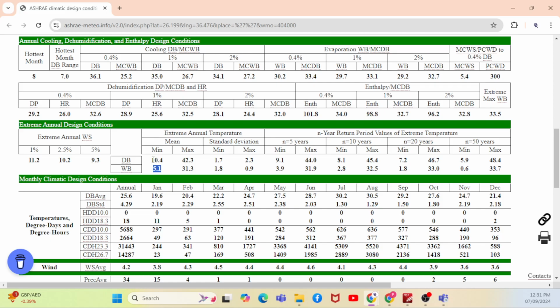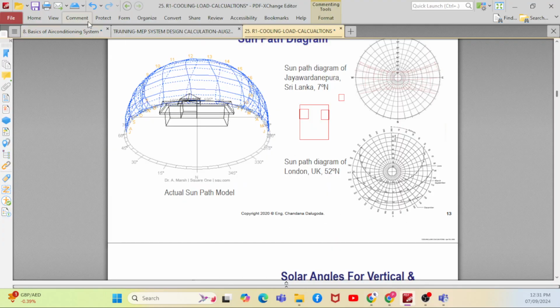When you talk about winter outside, this is the outside temperature, 10.4 degrees Celsius. Similarly, it is the same case. Just now, whatever we have calculated, what is the heat inside? The heat coming from occupants will not change during winter and during summer, right? Whatever heat you have from your body, it will emit the same heat. Maybe it will vary depending upon the activity, but the amount of heat will be much more equivalent. The heat from the light, whether during winter or summer, the same amount of heat will dissipate. Your computer will dissipate the same amount of heat. The only change is your external portion. So there is heat available inside your space. Clear, right?